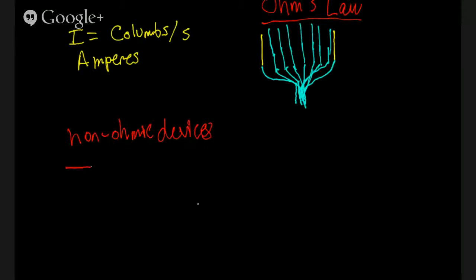So let's get into the components actually. What is a resistor? Usually it's made out of carbon. We use this schematic symbol for a resistor. Sometimes it's also just drawn as an open box. A resistor could be anything. Any conductor, if it's not a superconductor, will have an inherent resistance to it. The thinner the wire is, the higher the resistance.